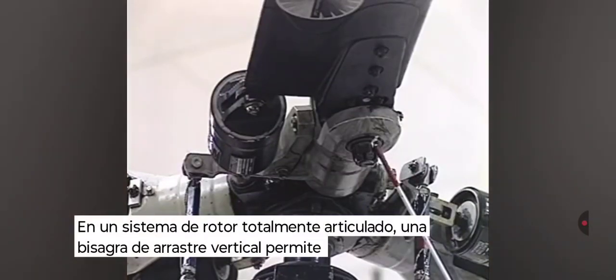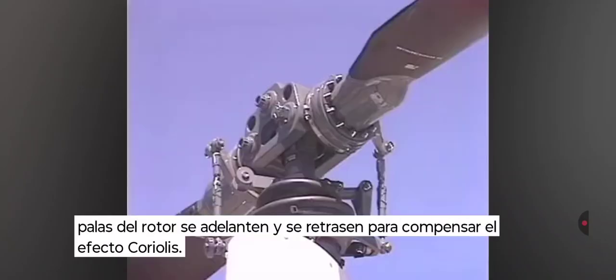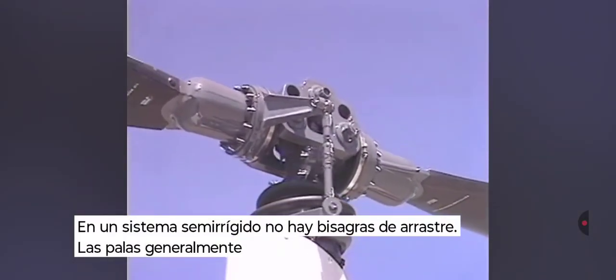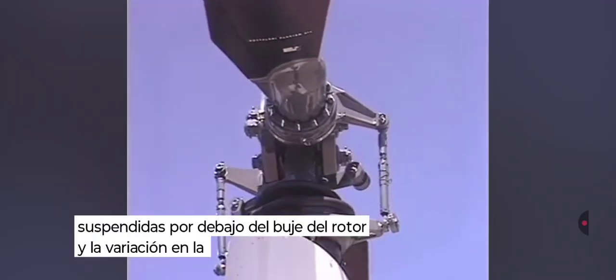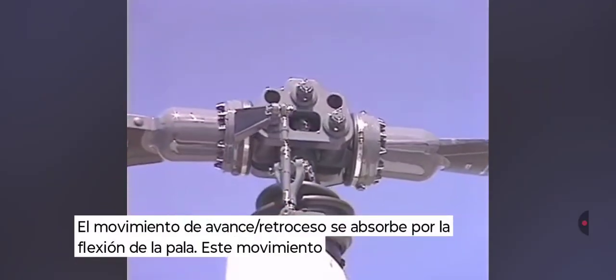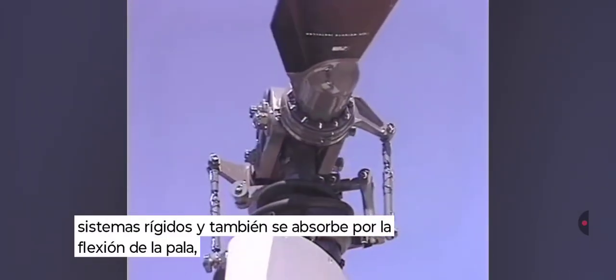In a fully articulated rotor system, a vertical drag hinge allows the rotor blades to lead and lag to compensate for Coriolis effect. Notice in this two-bladed system, there are no drag hinges. In a semi-rigid system, the blades are generally underslung with respect to the rotor hub, and the change in the distance of the center of mass from the axis of rotation is small. The lead-lag motion is absorbed by the blades bending. Lead lag is usually not significant in rigid systems and is also absorbed by blade flexing and bending.